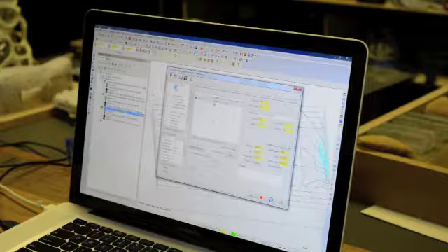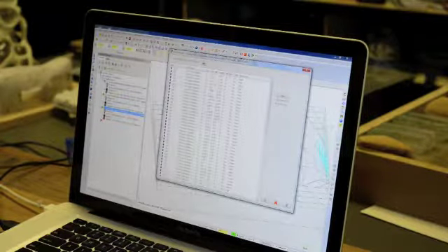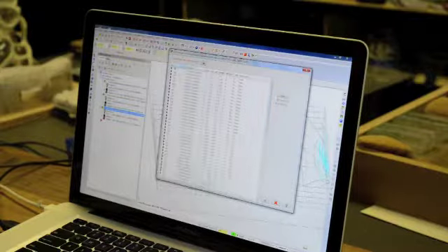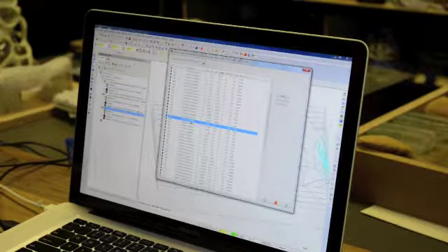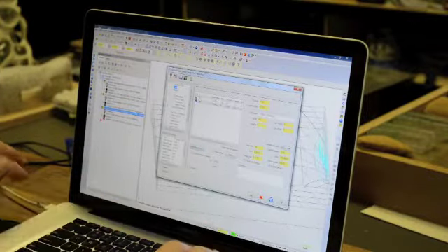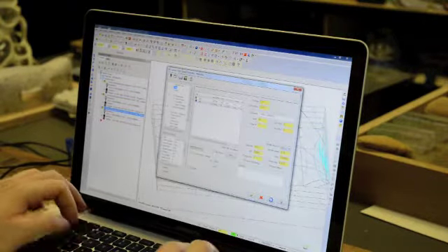And so for a tool we use that 1/2 inch flat, but now we're going to do a finished tool path and would like it to be quite smooth. So let's try, for example, a 1/4 inch ball nose. I believe that's 252. Okay, so feed rate, start off at the maximum 500 and we'll do a plunge of 200.